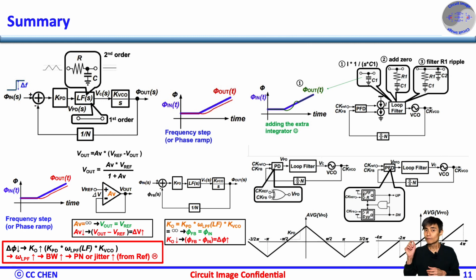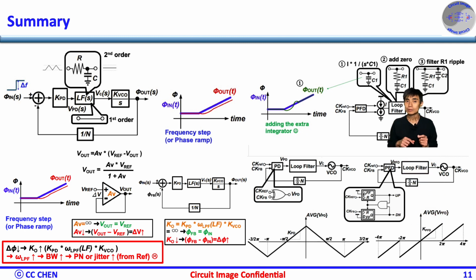Therefore, a phase frequency detector, PFD, with a constant slope and polarity asymmetry about the zero phase difference can extend the wide frequency pulling range. Also, the PFD output can match the following integrator, with a charge pump to a capacitor C1, properly to realize a type 2 PLL and eliminate the issues or design constraints from the type 1 PLL.